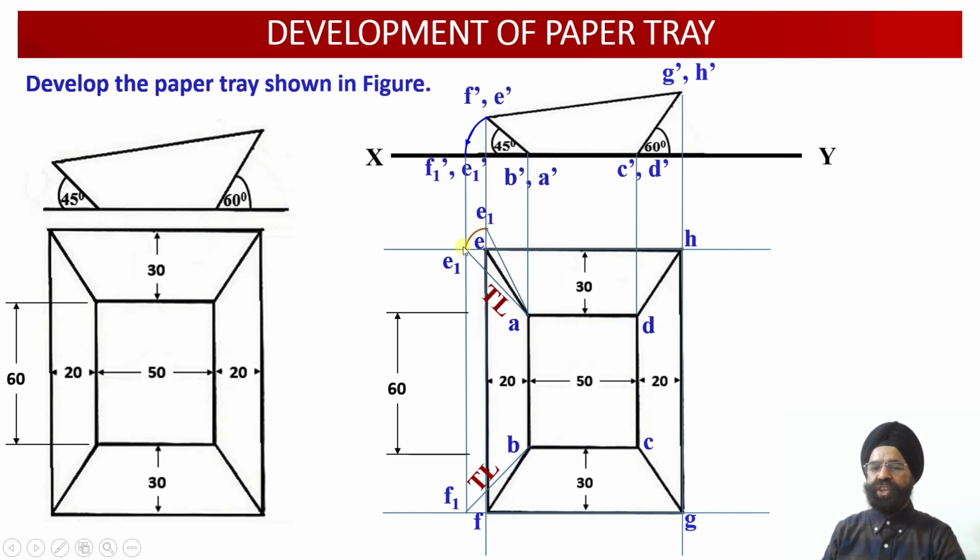That is, this is the location of point E1 corresponding to the vertical orientation. Now we have transferred this into the horizontal orientation over here, so that the second face we should be able to evaluate over here. So now this point E1 from the vertical orientation has been shifted or transferred into the horizontal orientation, so that this face true shape we should be able to obtain over here. And these two edges, they should be having the same edge length over here.